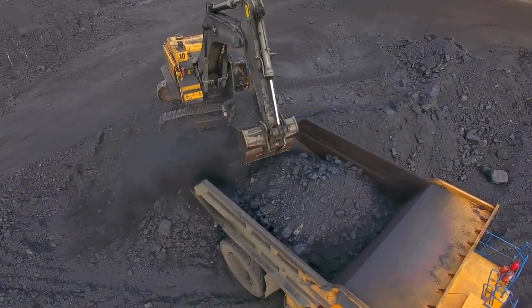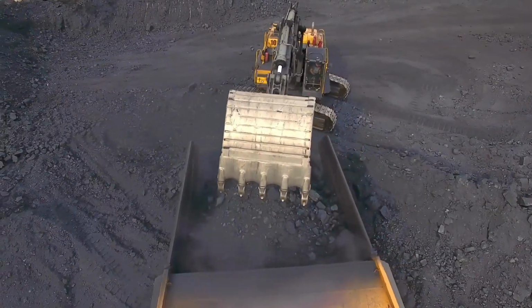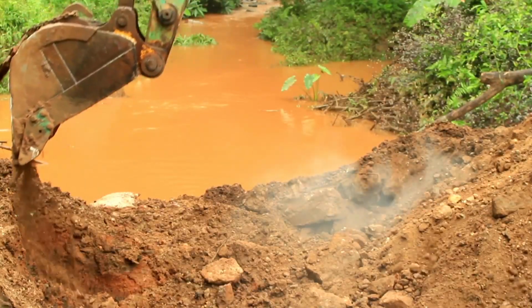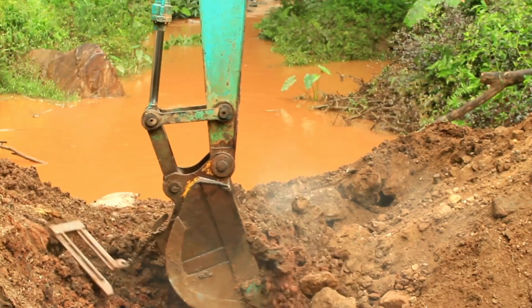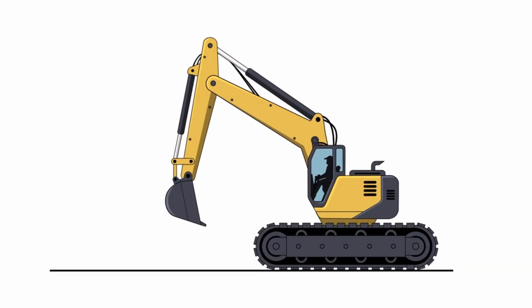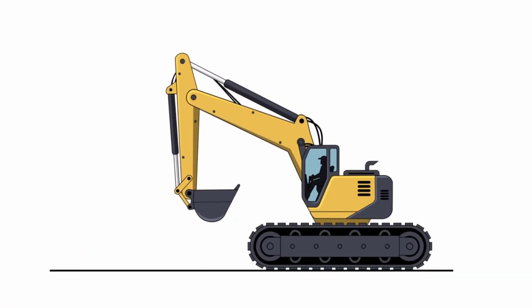Each part of the chain has a specific role. The boom raises and lowers the entire working area. The arm controls reach and digging depth. The bucket performs digging, curling, and dumping. Even though hydraulic cylinders move in straight lines, the joints rotate. Kinematics explains how straight-line hydraulic motion is converted into smooth angular motion at each joint.